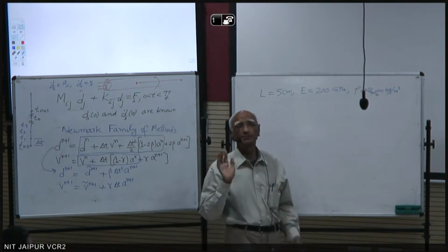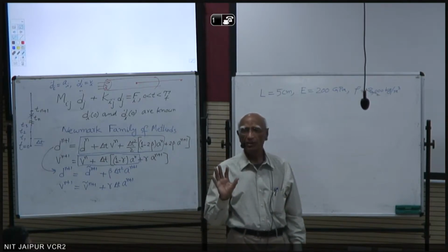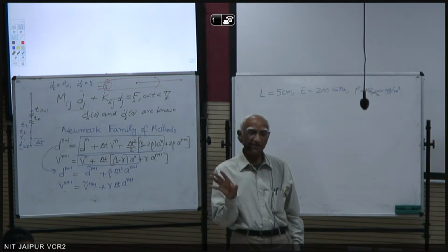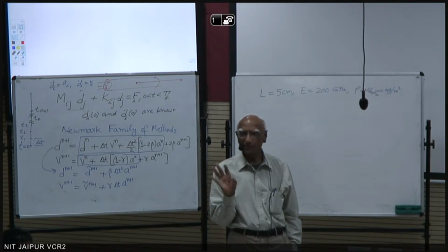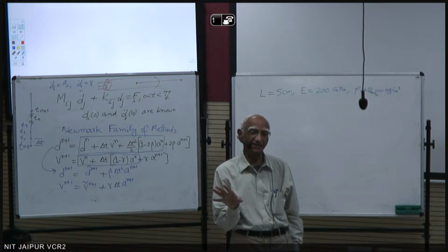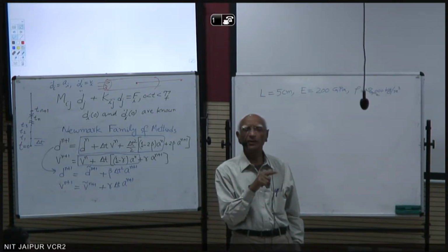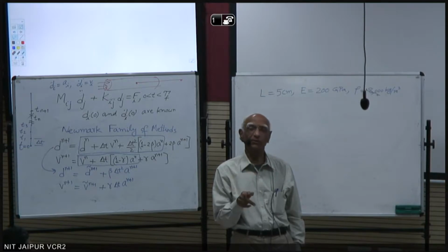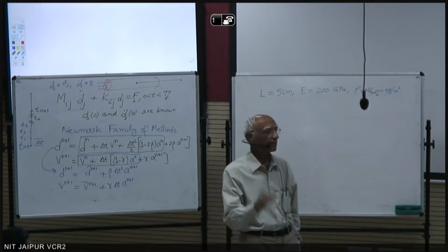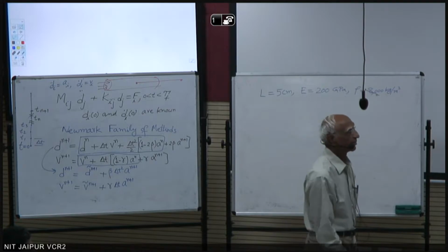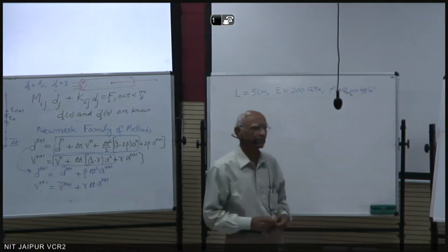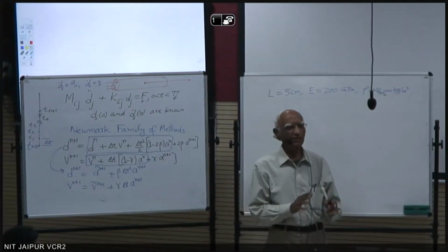One thing more. If you want to get an excellent solution, then we have to assemble the mass matrix again, because we have to use the mass matrix with R equal to 1/12. But that will give you an implicit method. Let's use an explicit method.